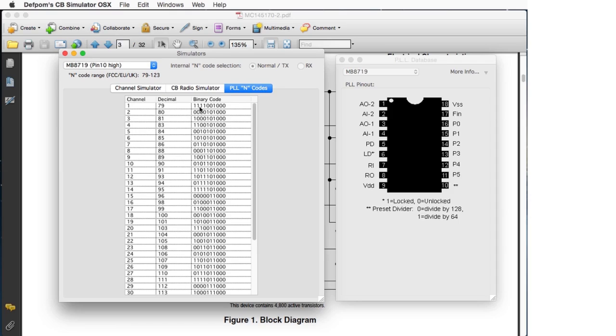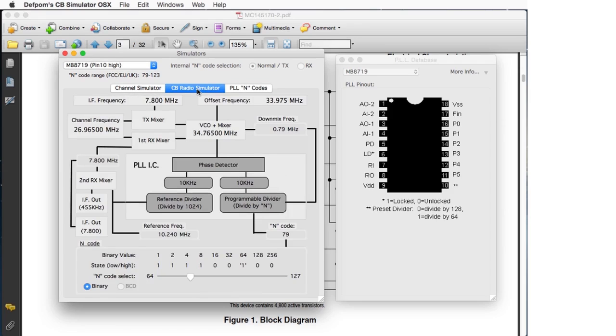Externally, pin 10 is inverting, so it actually works backwards from what you expect. Anyway, it's a bit interesting, but the way they work it, when pin 10 is high, it's actually low, and when it's low, it's actually high over here on the 128. But yeah, it all works the same way, and that's it. So that's how they function.